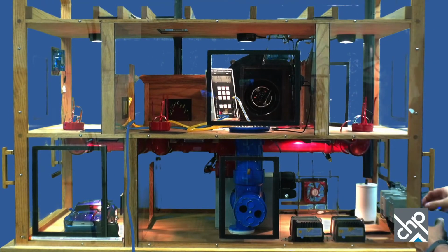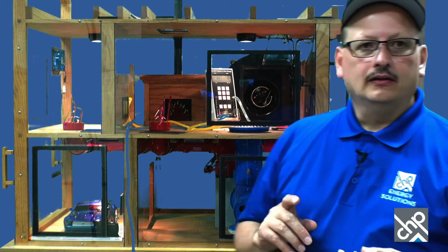All right, so now for a CAZ test, what we want to do is, like I said, go to natural conditions, or let's say winter conditions, where you've got all the equipment off: exhaust fans, air handler fans, combustion equipment on pilot. If you've got a gas water heater, or your thermostat's off, any combustion appliance, you don't want those to fire up during this test. Same way you don't want them to fire up during your blower test.